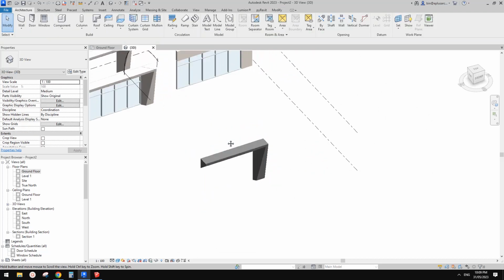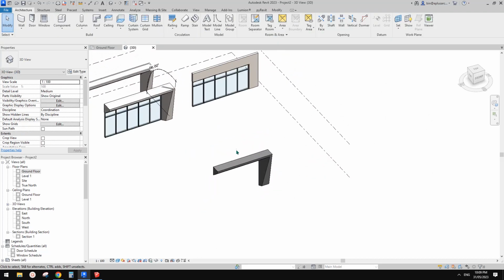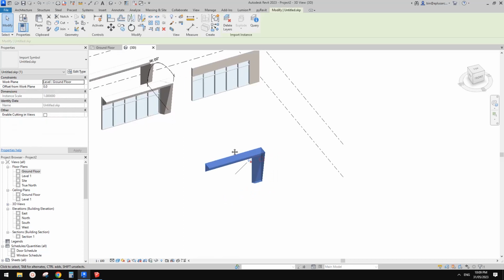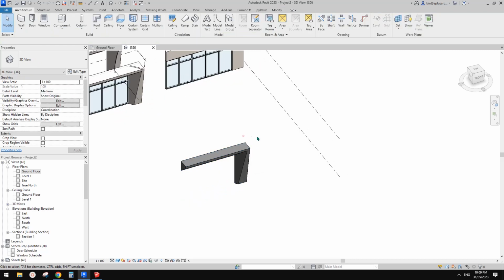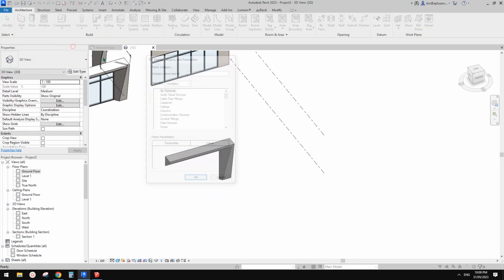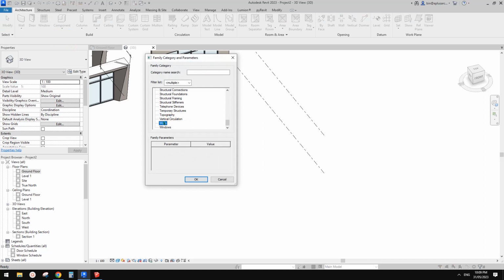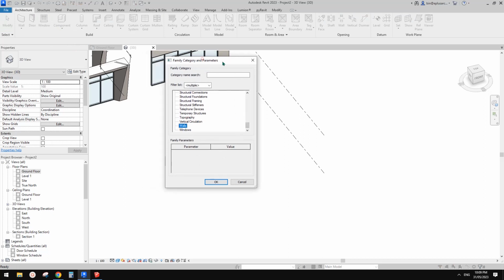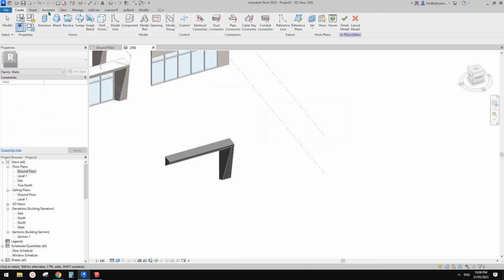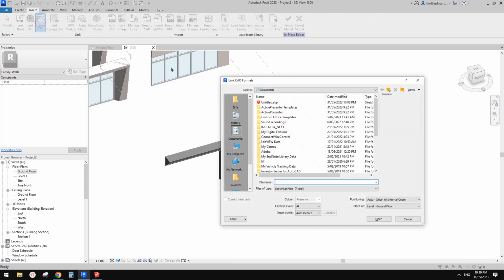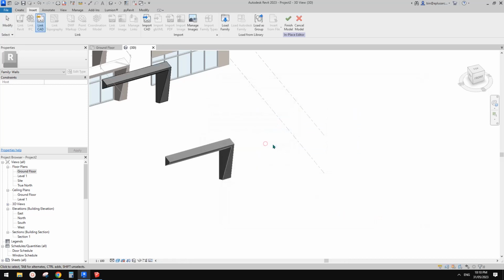So what we need to do is quite simple. If you just need this geometry and don't worry about placing a wall onto it, you can directly model in place a cuttable. For this instance, we can use wall, and then in this wall, just do the link CAD or import CAD again.